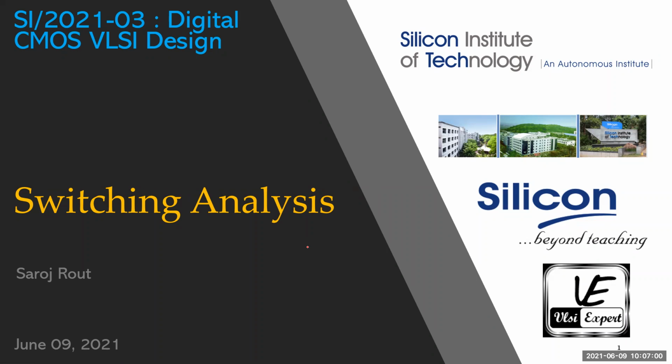And today we are going to continue on what Santanu has taught you guys on delays. So we'll do some switching analysis. And mostly what we'll be talking about is, I'll introduce you to the formulation of delays in CMOS gates. And then we're specifically going to look at how to optimize the buffer. So when you have a big capacitive load and you want to drive it, how to create this buffer chain or set of buffers to drive it with a minimum delay for a given technology.